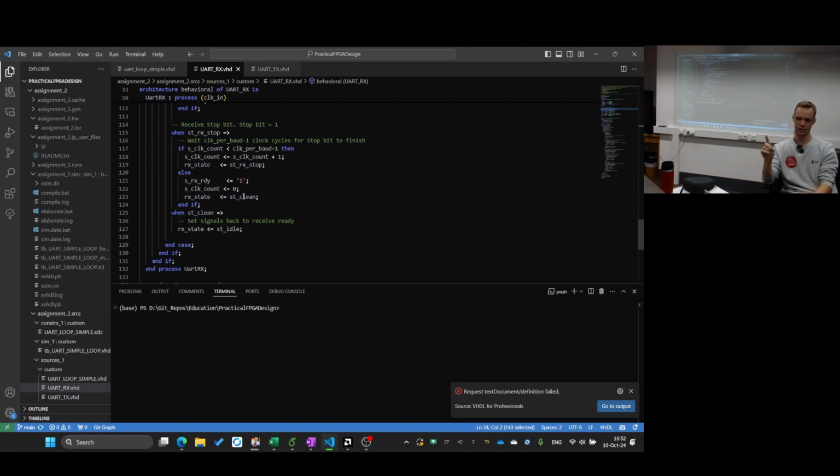And actually the synthesis, in this case as I've put it, does not give you a warning, because it creates an unintended latch or unintended flip-flop in that case. It will not warn about that, because it assumes that this is wanted. But you will see in the simulation that your simulation will not look as it's supposed to.